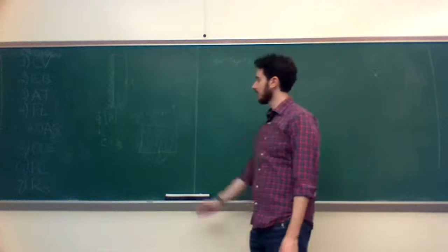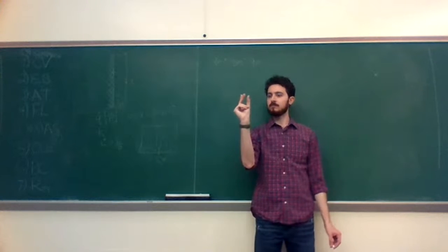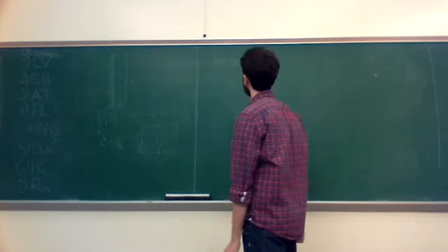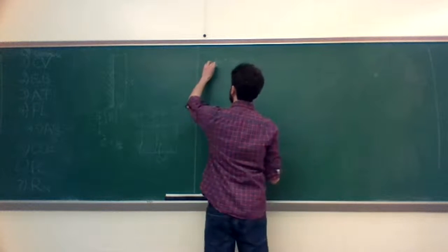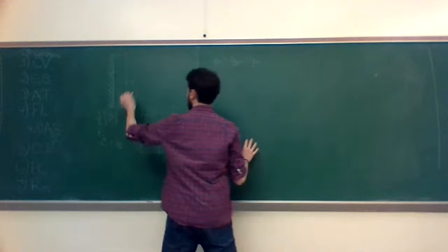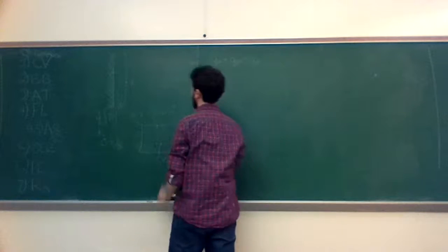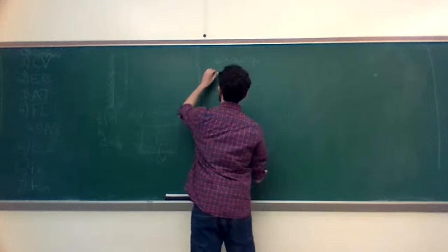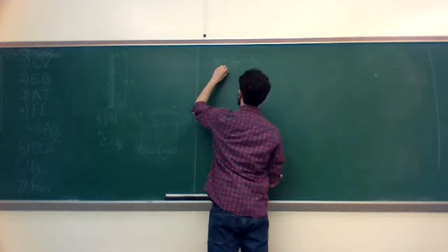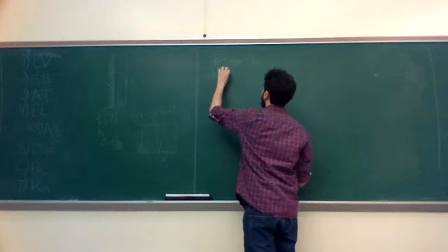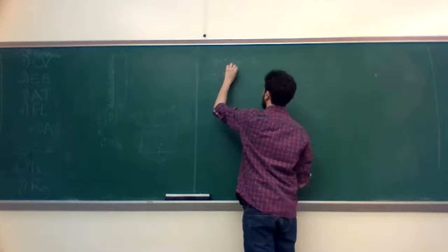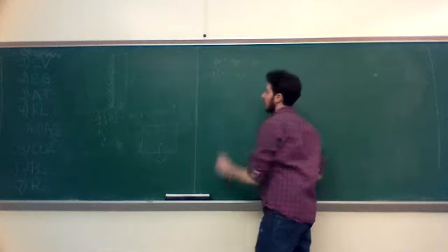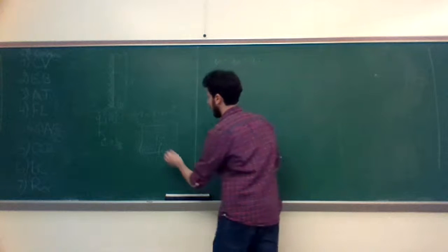Over a differentially small element, Q gen is going to be infinitesimally small, right? But again, calculus tricks. So the other way to write this is Q in is your heat flux Q evaluated, and the convention is this is just one dimensional across the x-axis going to the right, Q evaluated at x, plus Q gen. And Q gen, since we're assuming uniform volumetric heat generation, is Q dot times the volume of this control volume.